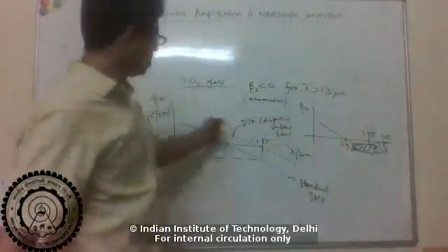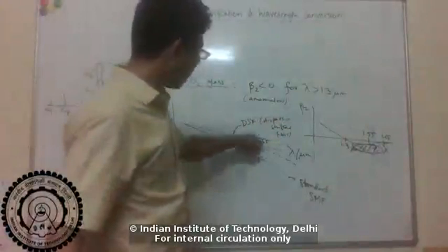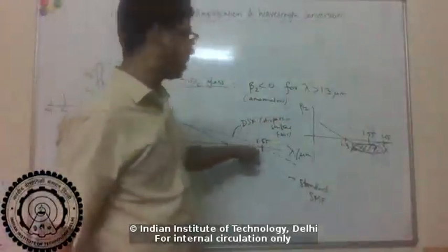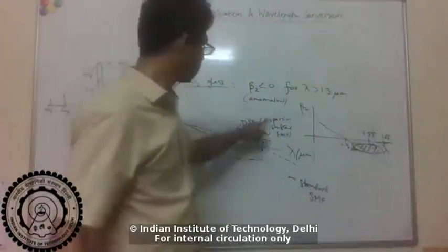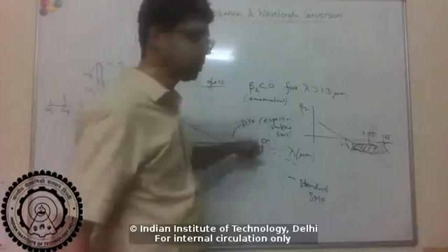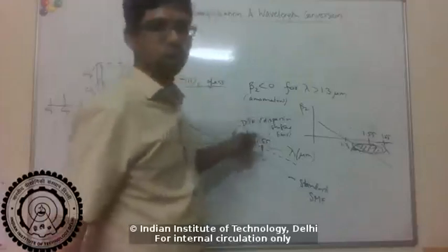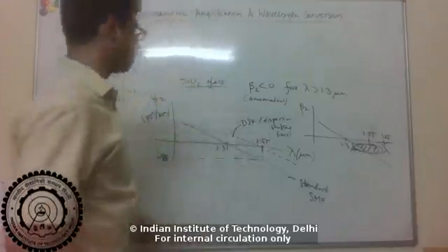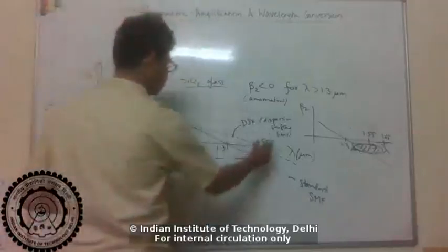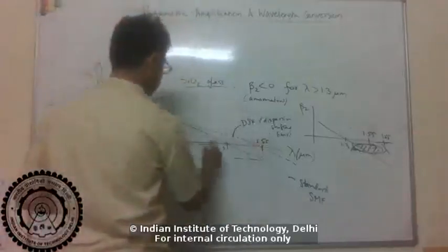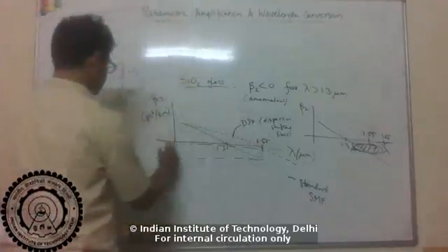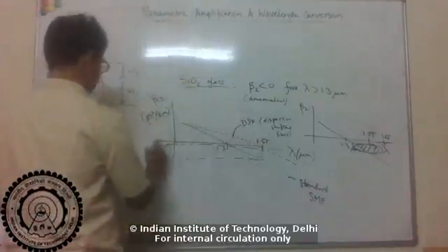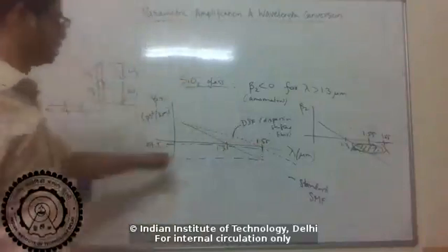Right, so with this, you can get near zero dispersion at the low loss wavelength of 1.55. That's basically the best you can do. You have zero dispersion and the lowest loss, so you can propagate the furthest distance. Right, so for this, you can get the dispersion down to as low as like 1.1 to 1 picoseconds per kilometer.